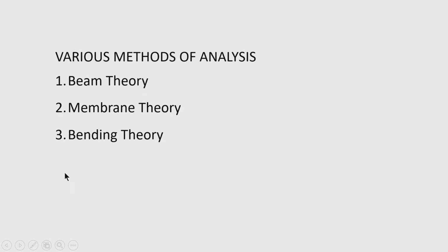Then I will also take the snow load, which is a load acting over the horizontal projected surface. Okay. There are various methods of analysis of cylindrical shell. The one common method is beam theory, then second is membrane theory and bending theory. The beam theory is an approximate method. Membrane theory is also simple, but a very attractive method because it gives the true picture of stresses except near the supports. Bending theory of course is complicated, that includes the bending moment near the edge of the shell, and that bending theory has been developed including the results of membrane theory.